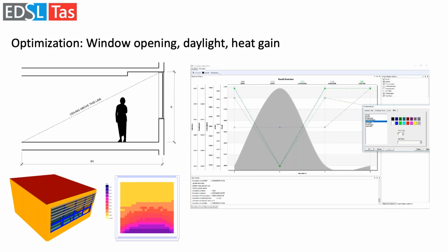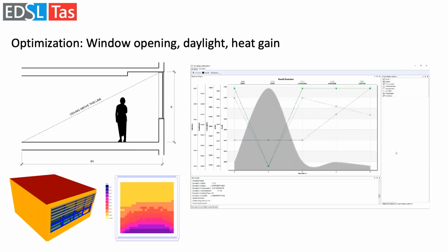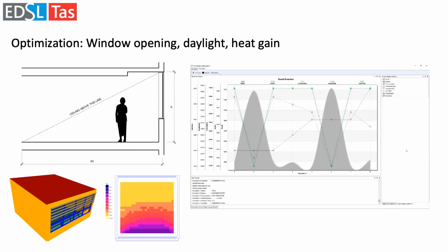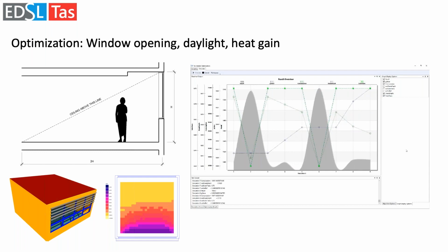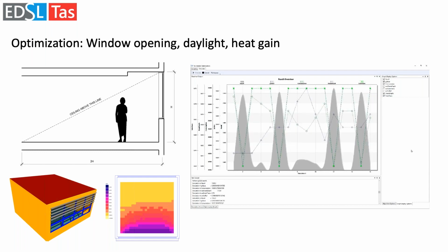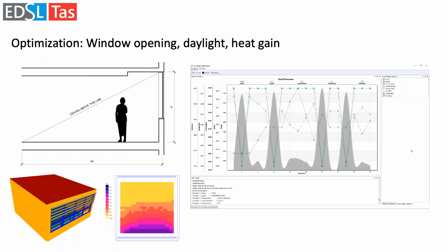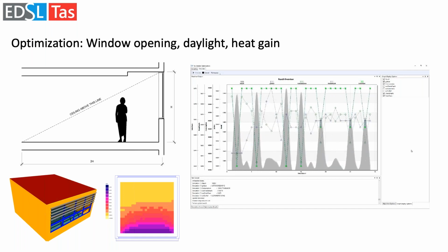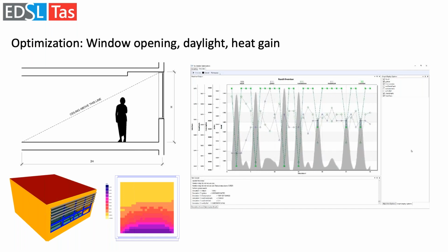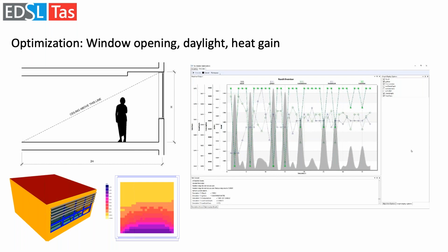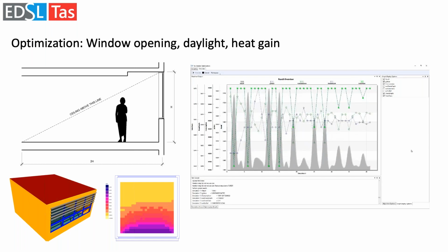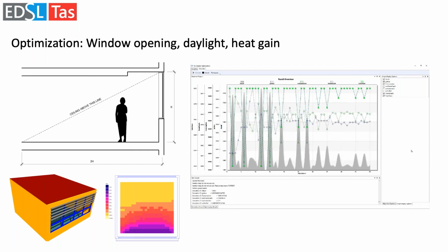So when you can't find a clear solution for many things in building simulation, because lots of variables overlap and result in different outcomes, optimization can help. You can take a few things like shading and daylighting, calculating maximizing daylight availability and minimizing peak cooling load. And this is basically running a series of options.